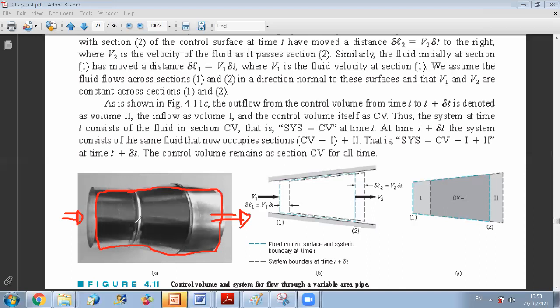So, for example, I can consider that at a certain time t, my nozzle is full of particles. Let me define at this instant t my system as the fluid particles inside the nozzle at time t, and my control volume is bounded by the nozzle inlet and outlet. If my nozzle is fixed and I have a flow of particles over it, then at any time t, my control volume will be limited in this example by the same geometry, while my system will be moving.